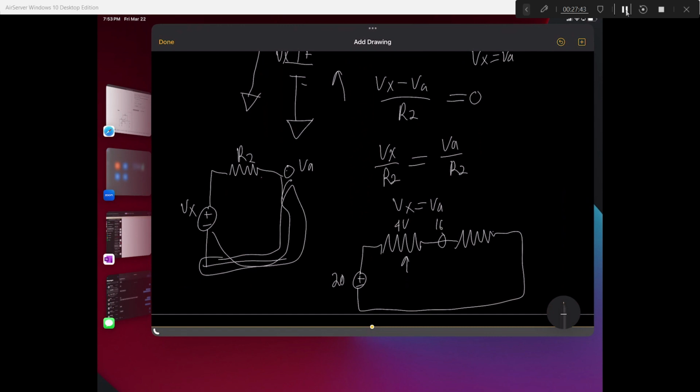Now this next resistor has to get rid of all the voltage no matter what. If we make that an unknown, it's going to be a 16-volt drop. So this is going to be 0 volts over here. Now once you reach 0, after passing through all the resistors, when you try to read the voltage at these points, it's going to be equal to 20 volts, if you were to take a multimeter and read it.